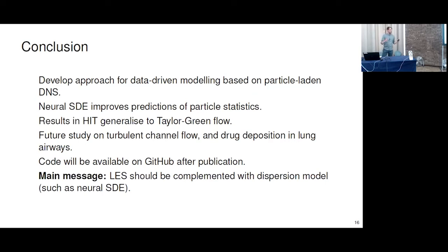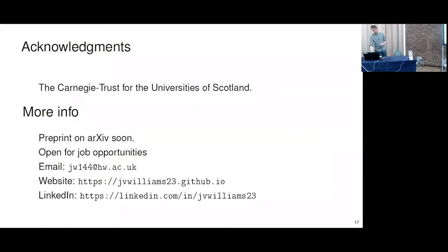But the main message is that LES should be complemented with some dispersion model and simulations of particle dispersion. Otherwise you get really mesh-dependent results, like kinetic energy. And we feel that the neural SDE is a really good approach for this, as it's been quite well validated here.